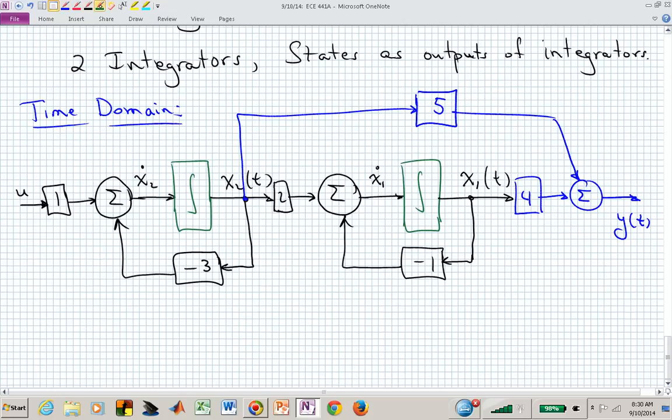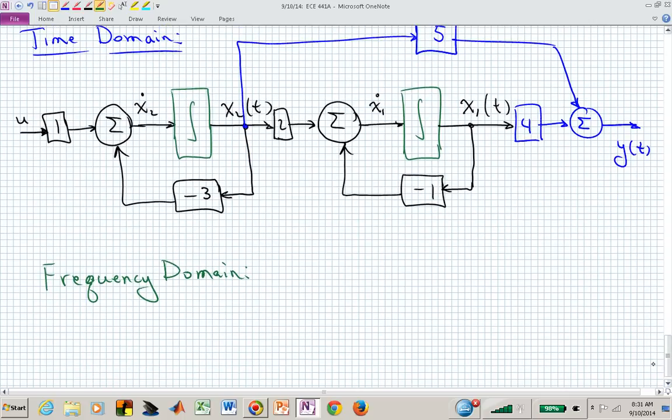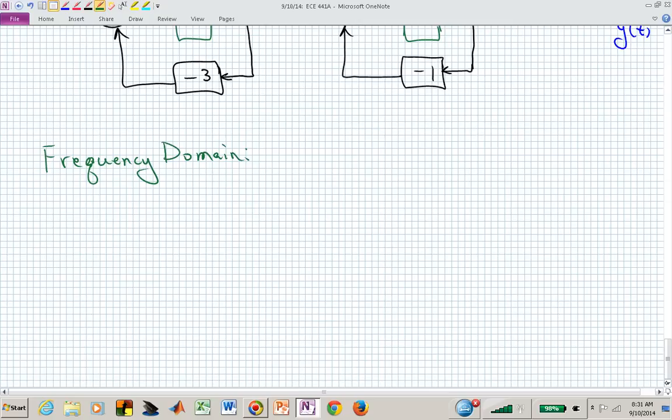Now, we've spoken before about GIFs in here. I don't know how giving I will be this semester, but if I was so kind as to say, give me the frequency domain block diagram for that system, could you do it? And what does it involve? Just change the integrators, erase those little squiggles, and replace those with 1 over s's. And then you have your frequency domain block diagram. And that's what we use to create our transfer function, which is the next step in our connection process.